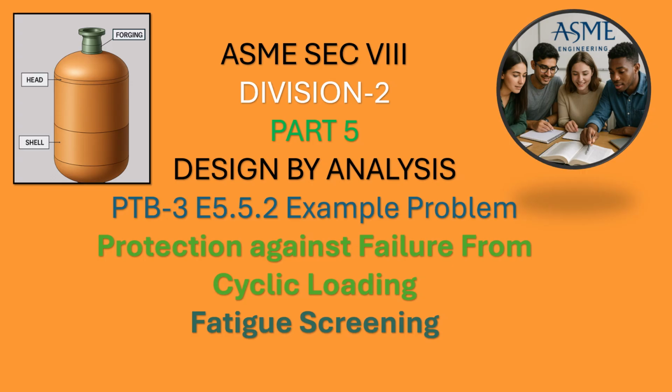So far in this series, we have covered protection against plastic collapse using elastic limit load and elastic plastic methods. And we also looked at protection against local failure using both elastic and elastic plastic criteria. Now we move into what is arguably the most important section in ASME design by analysis: protection against failure from cyclic loading and fatigue. This is critical because fatigue is one of the most common failure modes in pressure equipment, especially under repeated pressurization, thermal cycles, and mechanical loads.